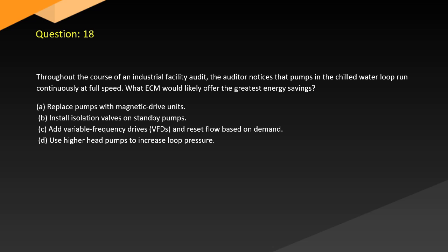A. Replace pumps with magnetic drive units. B. Install isolation valves on standby pumps. C. Add variable frequency drives, VFDs, and reset flow based on demand. D. Use higher head pumps to increase loop pressure.